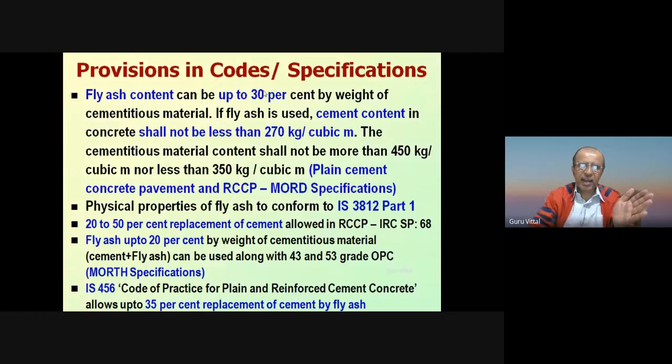They also have some limits for minimum cement contents. What about IS 456? That is the IS code for plain and reinforced concrete. It says that you can replace up to 35%, which is much more than this and this.